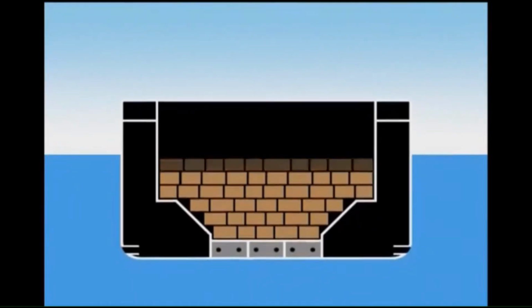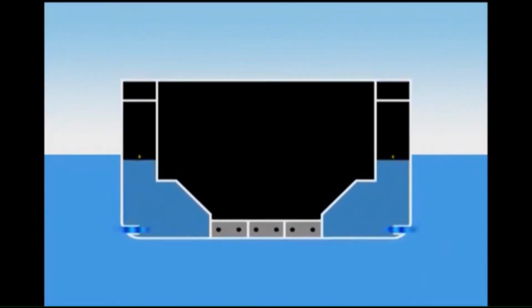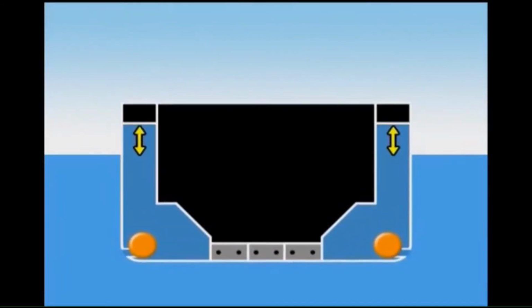As cargo is unloaded and the water level inside the ballast tank becomes lower than the sea surface, ballast water is gravity filled into the tank thanks to water pressure head of the seawater. Ballast filling stops when the water pressure head becomes zero, as the ballast water level rises to become equal to that of the sea surface. To continue to fill ballast water further from this state of balance, it's necessary to pump water in with a water pressure head higher than that inside the tank.